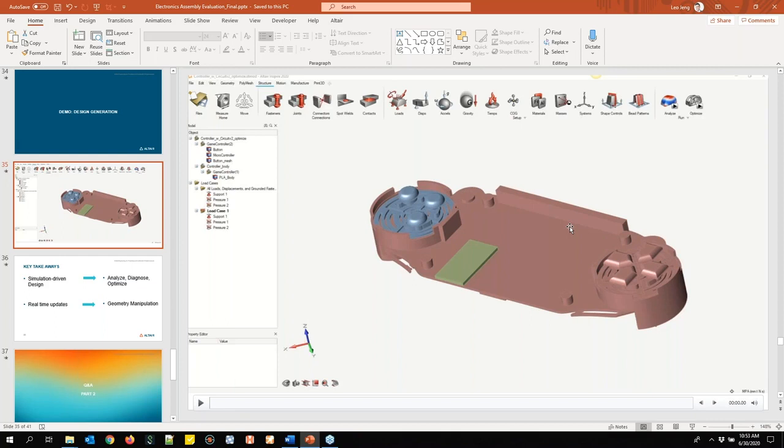I have some more questions coming here. Next one is, can we generate a finite element model from the setup you have shown? Yeah, so since this is all running finite element technology behind the scenes, this is not some random one-off tool. We're actually using finite element behind the scenes. We're just doing it a lot quicker, and we're enabling smart methods in the background to give you an optimized design. So it is still running finite elements, so we're able to export a finite element deck, so you can load that into your HyperMesh and other preprocessors that you would feel comfortable using.